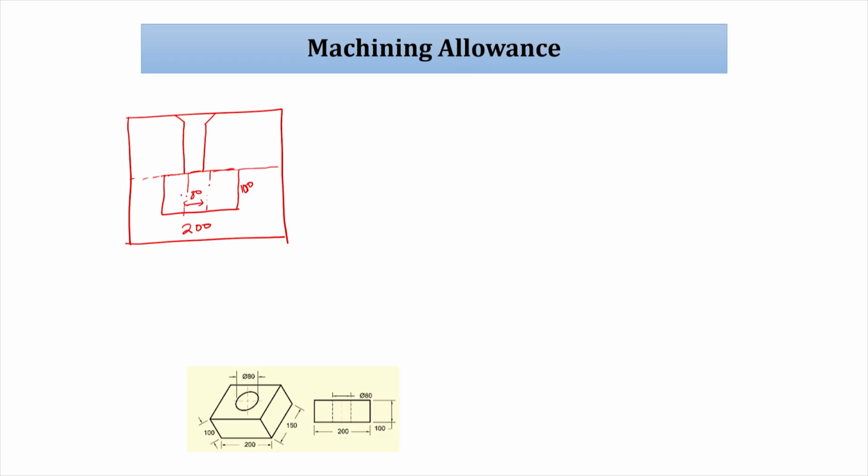Based on that idea I am creating machining allowances. So, machining allowance for any surface equal to 3 mm.